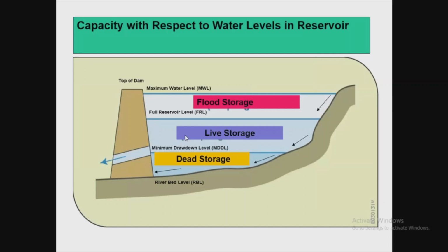So whenever I plan to allocate water for power supply, I have to reduce the demand by 20%. If somebody is asking for irrigation, I require this much million meter cube of water. But you can say, no, my capacity is encroached. I cannot give that much water because there is no water balance in the reservoir. At that time you can surely tell, okay, I have assessed the capacity of the reservoir, therefore I cannot allocate this water. Otherwise, what will happen?